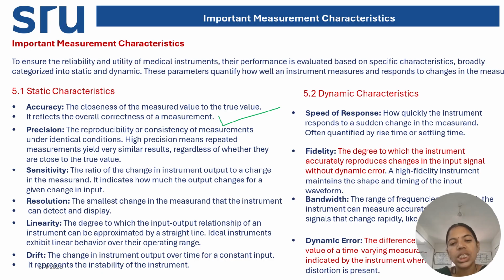Resolution, the smallest change in the measurand that an instrument can detect. Linearity, the degree to which the input-output relationship is linear. And drift, the change in the instrument output for a constant input. These are the static characteristics.